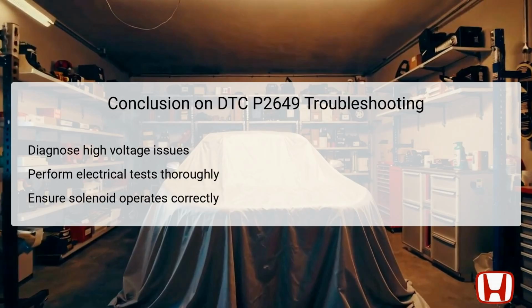In conclusion, diagnosing DTC P2649 requires a thorough understanding of the rocker arm oil control solenoid's role within the engine's variable valve timing system. By systematically performing electrical tests, including resistance checks and continuity tests, technicians can effectively isolate the fault, making necessary repairs or replacements.